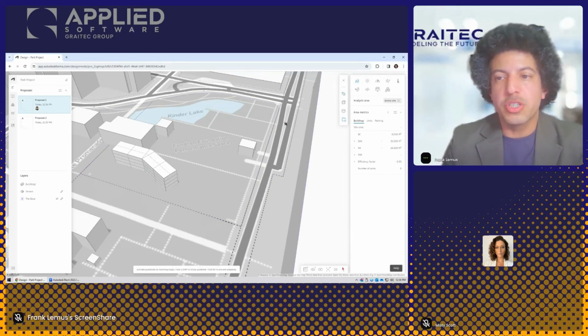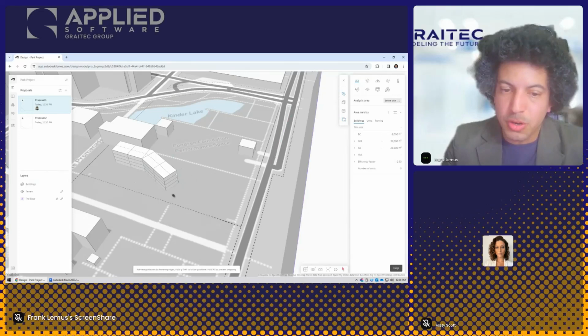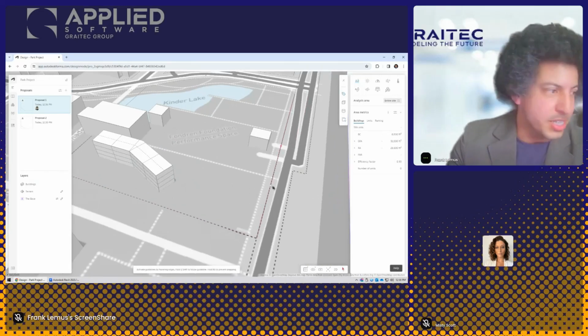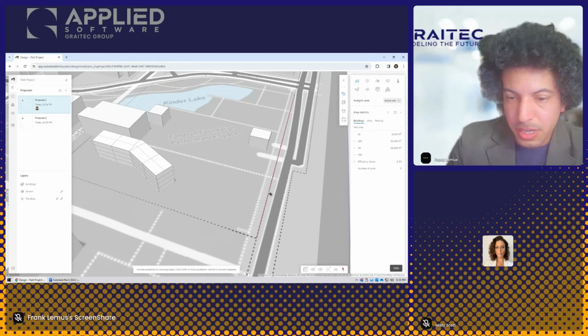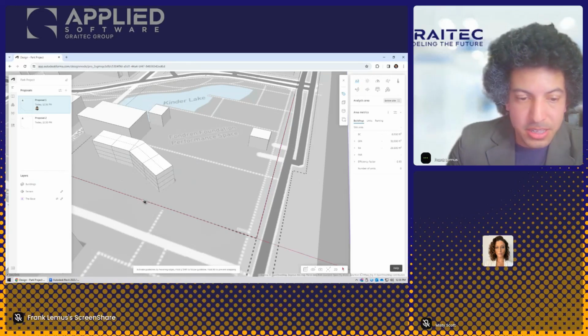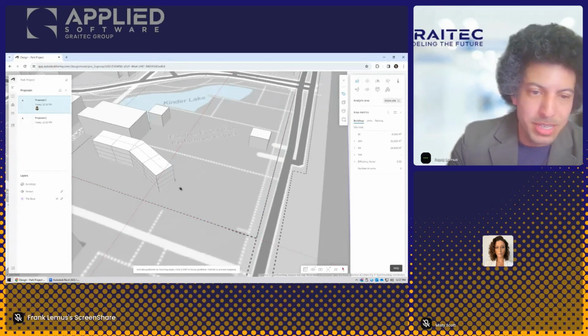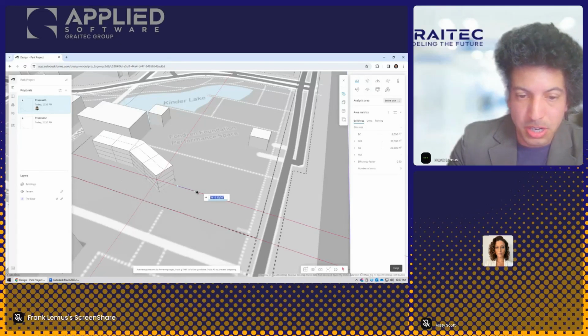I'm going to use Freeform just to show you guys a quick preview of the way these tools work. But this is not a training. This is just for me to show you guys everything you can do. You see here it does actually respect things. For example, I could say, look at the center. Hovering over it now allows me to use that line for something. In this case, the way I've placed this building, I'm not going to use it, so I'm just going to start here. But if I wanted to do something parallel, I can just highlight over something, actually this one, and it's already parallel.